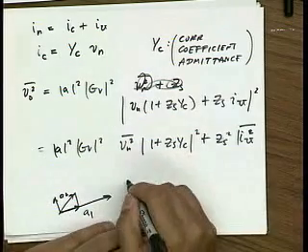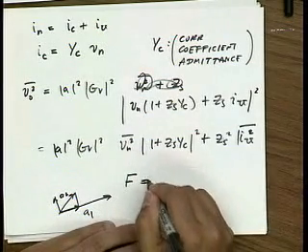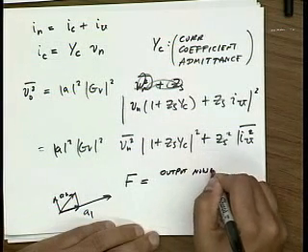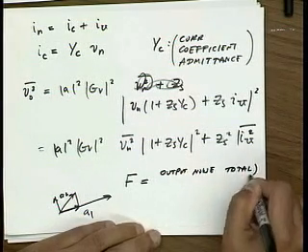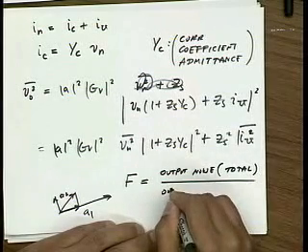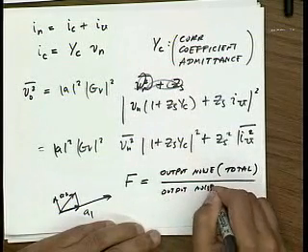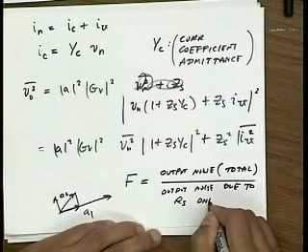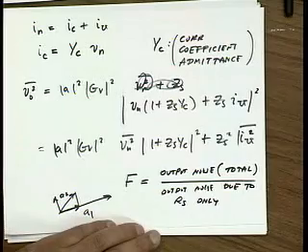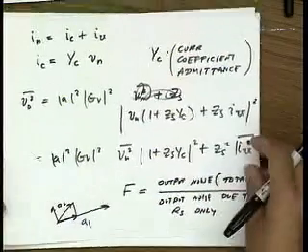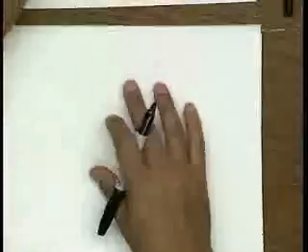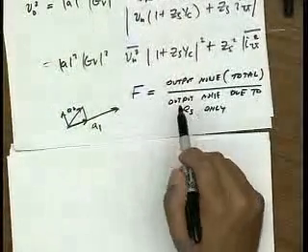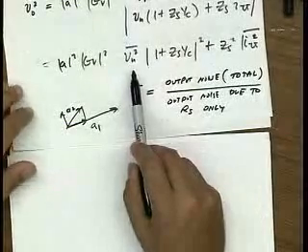All right, well, now we calculate noise figure. Noise figure is the total output noise divided by the output noise due to RS only. By definition. And this is a really nice, easy way of calculating the noise figure because the noise due to RS looks a lot like the noise due to Vn, right?